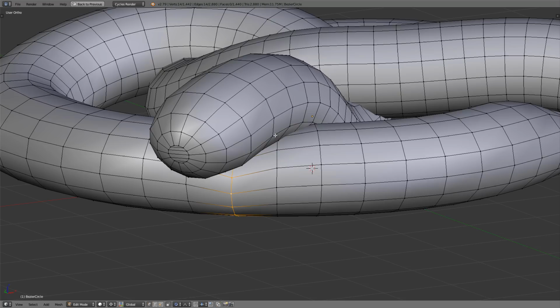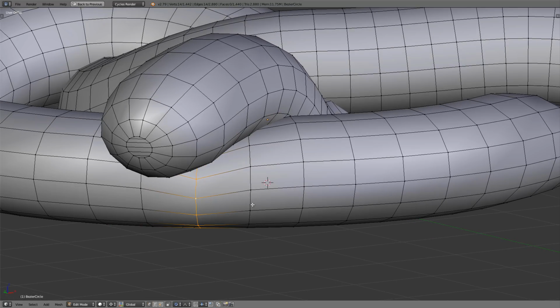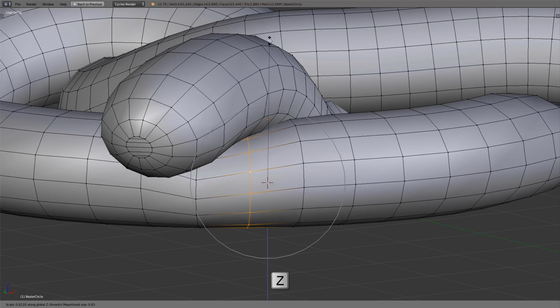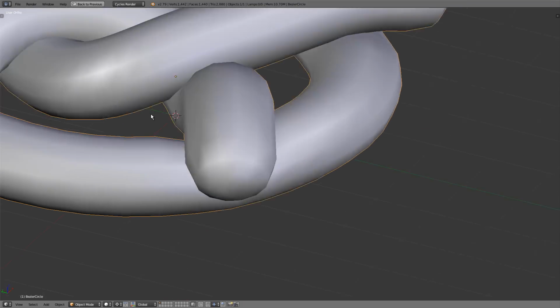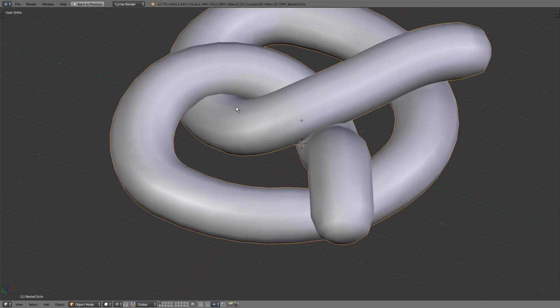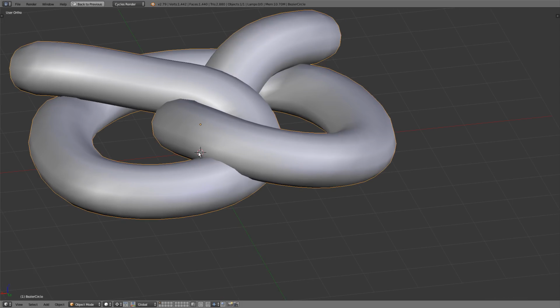However, we could use more of a dip over here. So I guess I'll take this edge loop as well and scale that on the Z axis too. So let me hold Alt, right click on that edge right there to select that whole edge loop. Then I'll press S and then Z and scale that down a little bit as well. All right, we got a good dip on this side, we got a good dip on that side, and we are good to go with them. So let's do the same thing for the intersection back here.